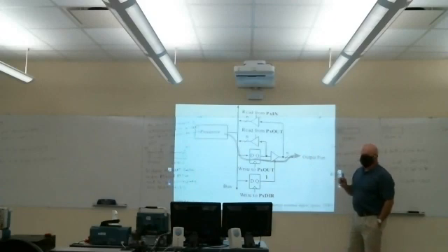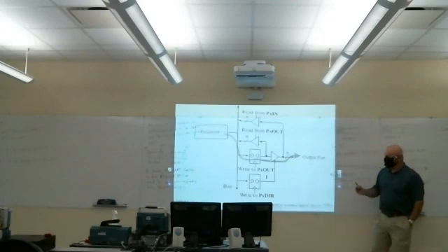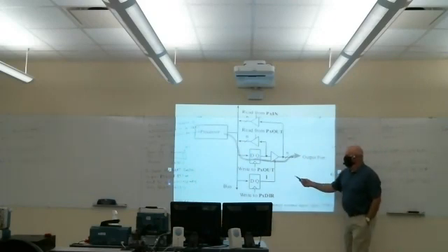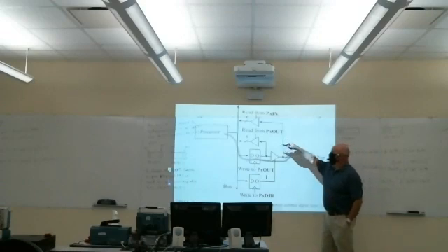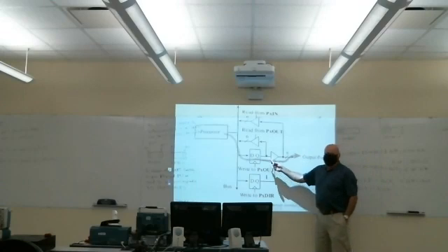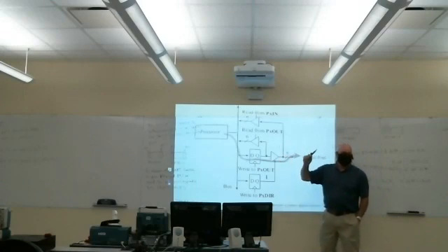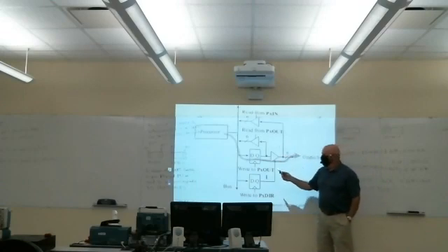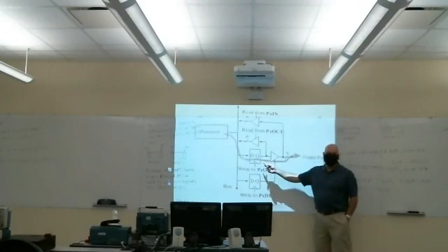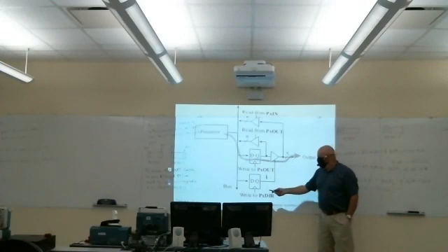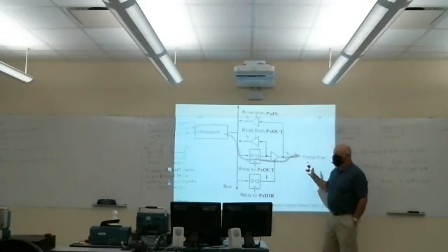Okay. Now, there's some other capability on the output ports on this particular microcontroller. It has what's known as readable output ports, which sounds strange, but once it's set up for output, if you want to, you can read from that output port to find out what was the previous value you wrote to that output port. Okay, so once you write to the output port, it's latched in this D flip-flop. And then you write that value, it's stored there. And then as long as this pin is high, it's output to the pin.